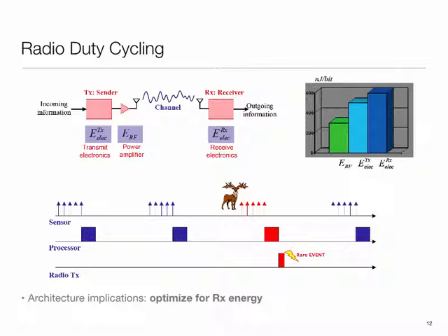Now, in particular, you can imagine applying this to, let's say, the radios. In the case of the radios, it would directly correspond to how much data you are able to send. Maybe you're collecting samples and your job is to ship them out. The more measurements you can take, or equivalently the higher the rate at which you can take the measurement, the better off you are. For example, if my radio wakes up every second for 10 milliseconds, then I am only able to send 10 milliseconds worth of data.